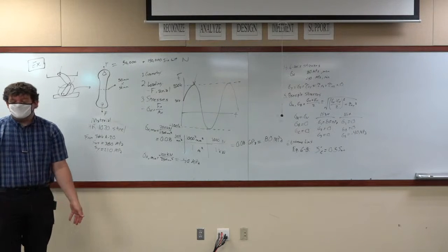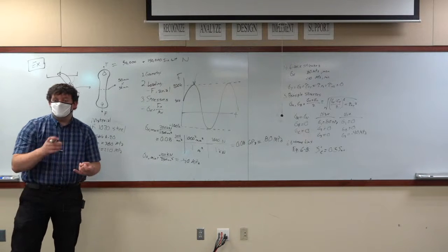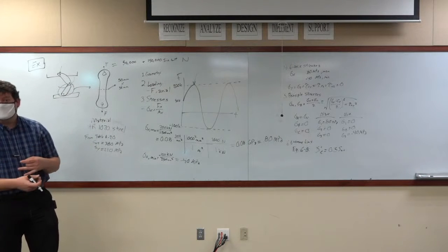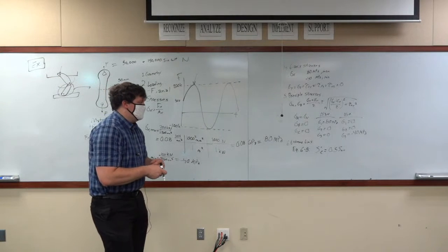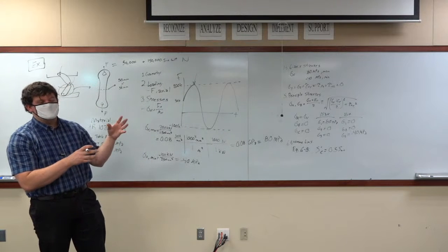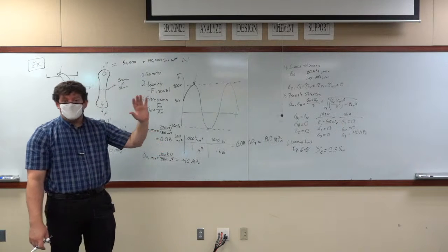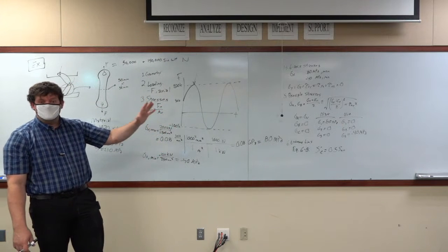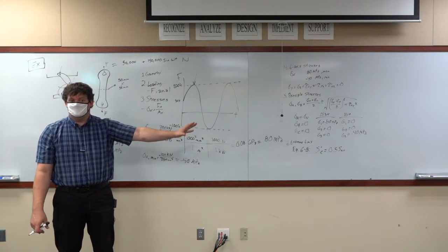It's not going to be able to tell you that in that table generic for all 1020 steel. It's very dependent on what material you're using. So, yes, you can find tables. If you find a specimen like yours that is loaded to a certain value, you can look up the endurance limit as tested, and use that straight value.